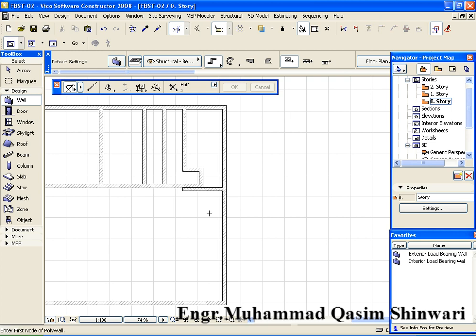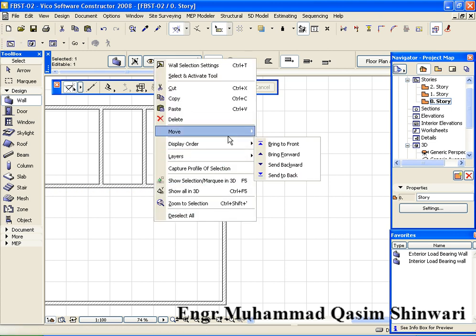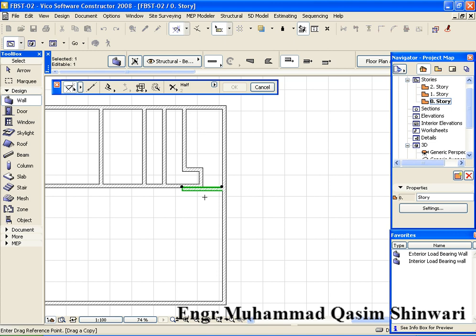It doesn't seem to be right. It should not be 24 feet. It should be 30 feet. Okay, select it. Now what I will do, I have selected it, move, drag a copy and bring it 6 feet vertically, and delete it. Control S to save your project.